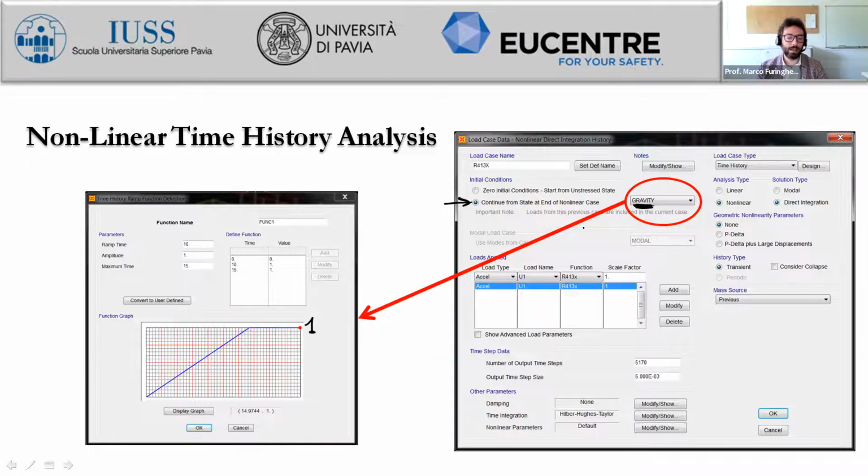This means that if we also account for other additional damping related to the overall superstructure, this may affect the isolation system, and maybe we are over damping the overall model, and we are underestimating displacements and consequently also internal forces. So what is generally done for seismically isolated structures is not to consider additional damping, since there is hysteretic damping within the nonlinear devices.